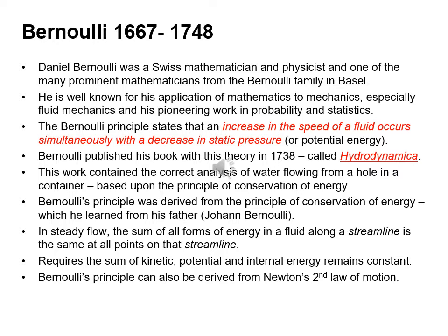This work contained a correct analysis of water flowing from a hole in a container based upon the principle of conservation of energy. Bernoulli's principle was derived from the principle of conservation of energy, which he learned from his father, Johann Bernoulli. In steady flow, the sum of all forms of energy in a fluid along a streamline is the same at all points on that streamline. This requires the sum of the kinetic, potential, and internal energy remaining constant. Bernoulli's principle can also be derived from Newton's second law of motion.